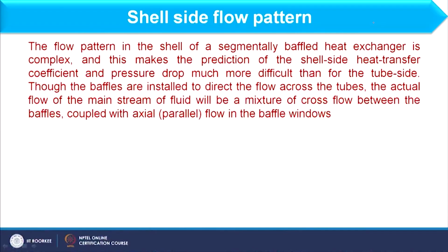Now, before going into detail of that, we will see what should be the shell side flow pattern. The flow pattern in the shell side of a segmentally baffled heat exchanger is complex, and this makes the prediction of shell side heat transfer coefficient and pressure drop much more difficult than that for the tube side.